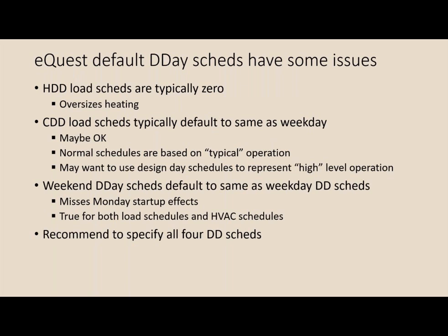So if you set up a model with the eQuest wizards and use default schedules that are built into eQuest, you find that there's some issues with those default schedules. For example, heating design day load schedules are typically 0. And my experience, that tends to oversize heating fairly significantly, and I'll show some examples of that further on.